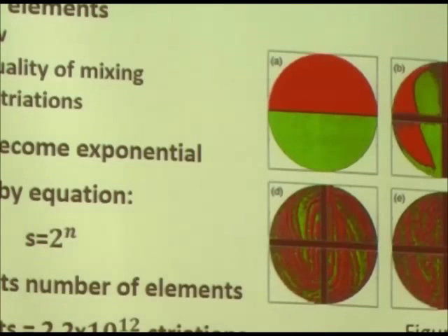Now, as you continue along, with more striations produced, it becomes very difficult to actually distinguish between the striations, which is what you want, because you want a good quality mixture, especially when you mix methoxide and the triglycerides, because they usually don't want to mix together. So with the 41 helical elements, the number of striations that you produce will produce a good quality mixture.